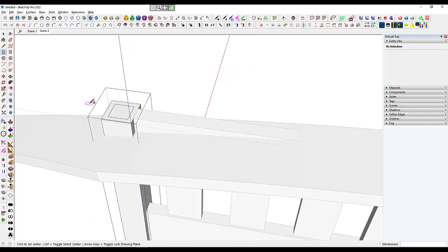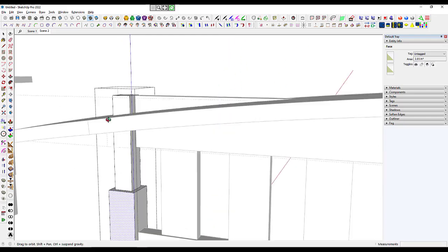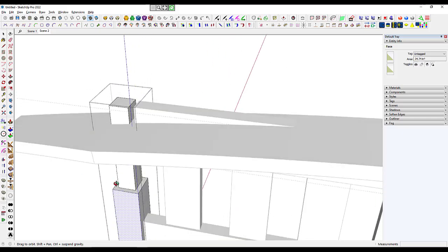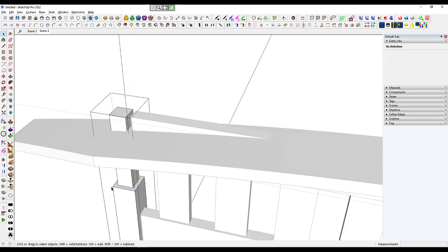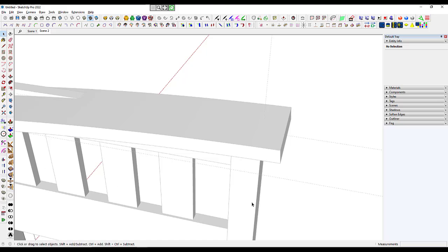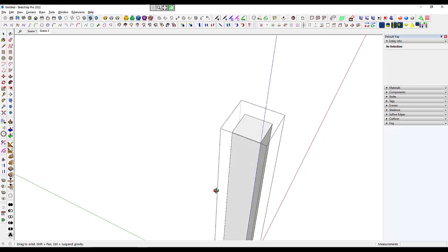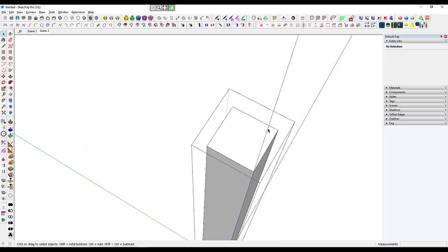and I'm going to temporarily push my shoulders down for that tenon, make it long. This is kind of a neat thing you can do with SketchUp that you can't do in real wood. Let's hide the rest of the model, and I'm going to do the same thing here. So for the rectangle, Control to do from the center, midpoint there, come in here, drag out.